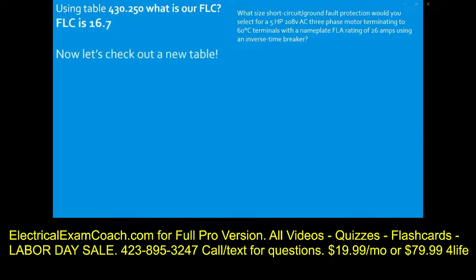Now we have to go check out a new table. Okay, so everyone head to 430.52, page 308 in the 2017, and page 319 in the 2020. When we get there, the first thing that we do is we read our black bold heading. It says maximum rating or setting for motor branch circuit short circuit ground fault protective devices. I feel like we're in the right place. Now on the left-hand side is going to be your type of motor, whether single phase or polyphase.